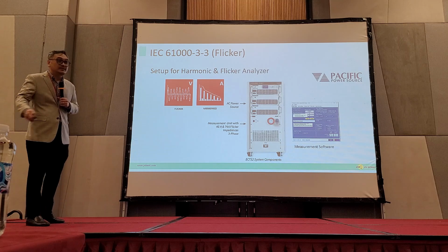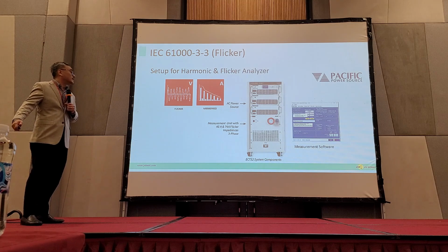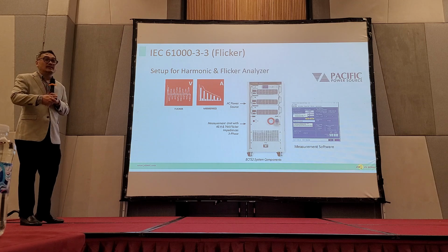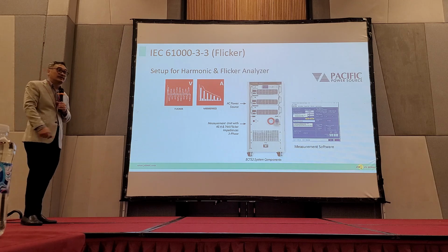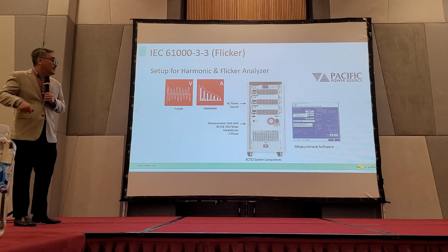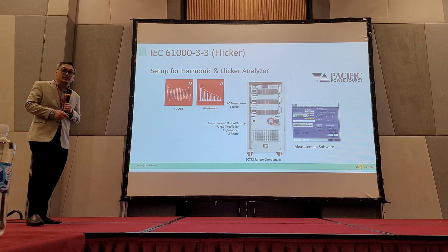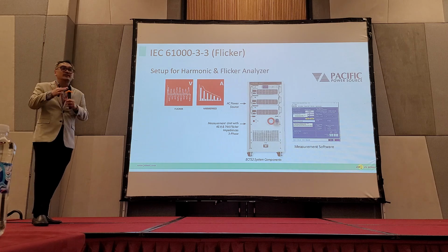We have single phase or three phase systems, depending on capacity, whether the product is single phase or three phase. So we measure the harmonics and flicker. Now we have finished the emission. We measure noise. Finished.